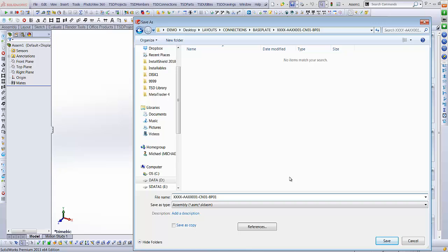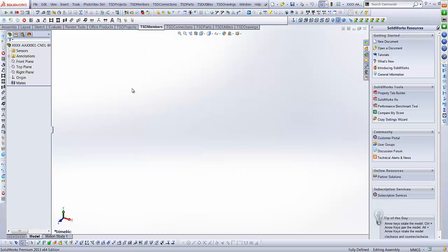And you'll notice that I don't like typing. If I can just copy something and manipulate it, it's much better than typing something, because if you type it, you're going to probably introduce an error there somewhere along the line. Alright, so rules are connection, same folder, same assembly name, just like the plate, same plate folder, same plate name. Okay, if you follow these conventions, you'll be right. Now we've dropped that in, so we've saved that assembly.